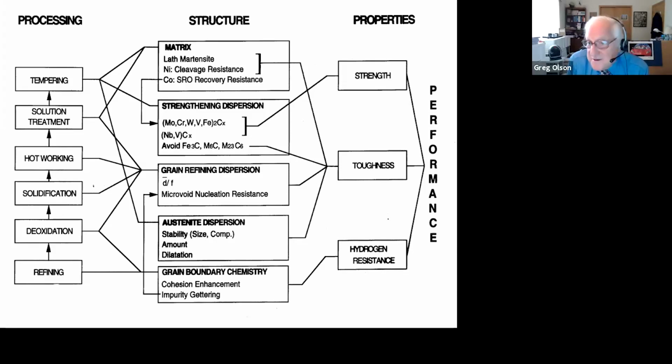Now, that can be done by empirical correlations that are useful for interpolation, but from the start, we were committed, by getting the most value out of the CALPHAD fundamental data, to use predictive science based on mechanistic understanding, and to express that mechanistic understanding in a form that we could parameterize, to devise parameters accessible to those fundamental databases.